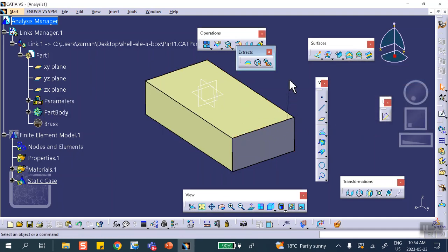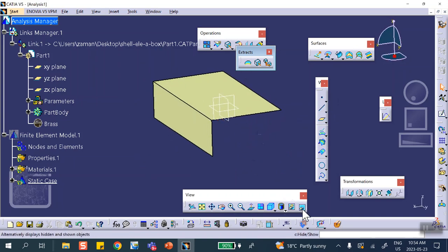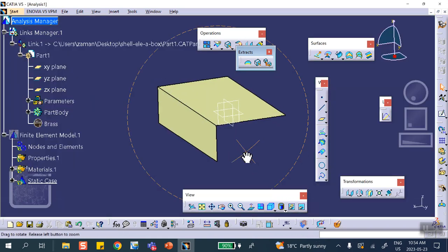So notice what we have done is to create those two surfaces. The ivory color indicates that you have a surface. In fact, I can hide this box, put the cursor there, right click and hide it. You have a surface. You can see that. That box is in the background, is hidden. You cannot delete this box because the surfaces come from that box. But at least we know that we have created the surface.